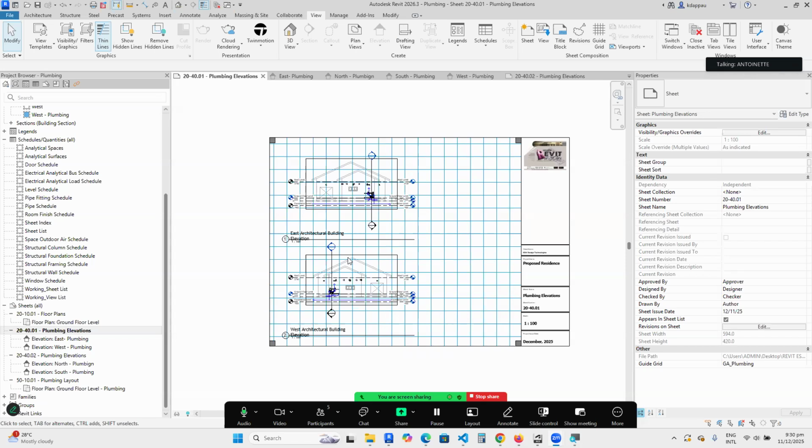Well, first you have to check, and we need to know which of the views you want to place on which of the sheets. For example, if you are using 1:50, if you are putting it on the sheets, probably it's only two views that would be on the sheets. So you need to decide which of the views, north, east, west, on that particular sheet, and then you center so that they are consistent.